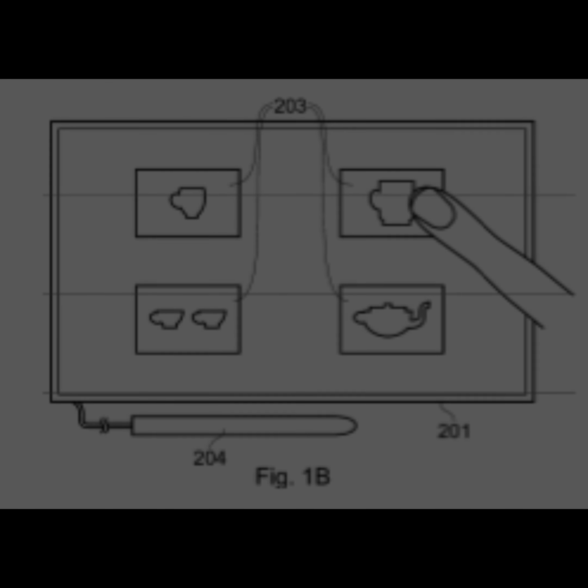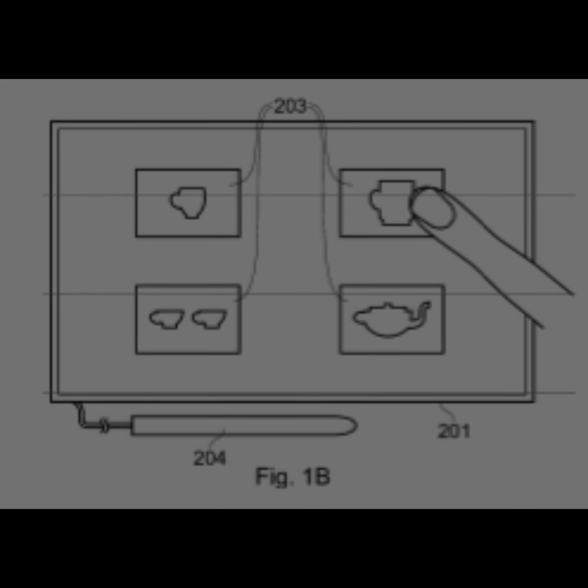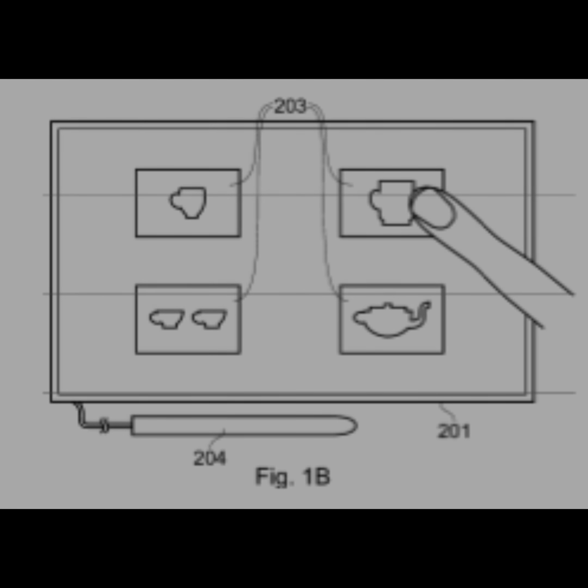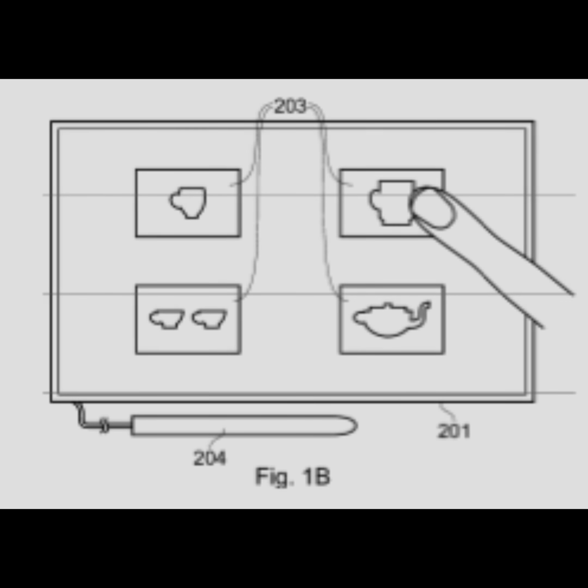A first pair of contacts A and B and a second pair of contacts C and D are provided at the periphery of the resistive layer 6. The resistive layer 6 can be connected to a voltage supply via the contacts A, B, C, and D. As shown in Figure 2, the control unit 9 comprises a switch 91, which alternately connects the first pair of contacts and the second pair of contacts to the voltage supply for consecutive time periods T1 and T2, repeating. The time periods T1 and T2 are defined by a clock 93.